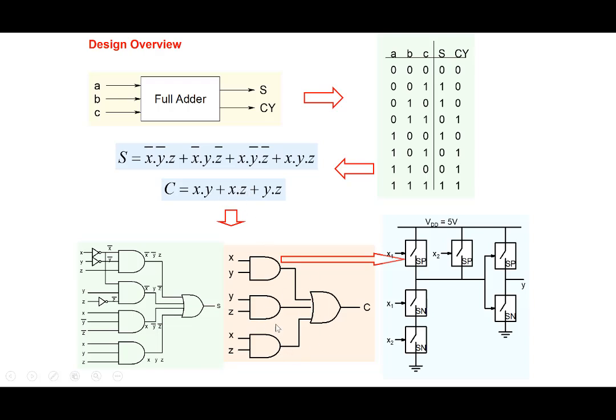Therefore, the simpler expression results in simpler implementation. The more complicated expression requires a more complicated implementation. Now, more complicated implementation basically means that I will require more transistors to implement. And therefore, the circuit ends up taking more area. Area in the sense that all these transistors are actually built on a piece of silicon. We talked about monolithic implementation. So all the transistors, all the interconnections, everything is done on silicon itself. And the larger the area of silicon that is used for making a circuit, the more expensive the circuit becomes. Okay. And so the complexity of a circuit is tied to the complexity of the expression here.